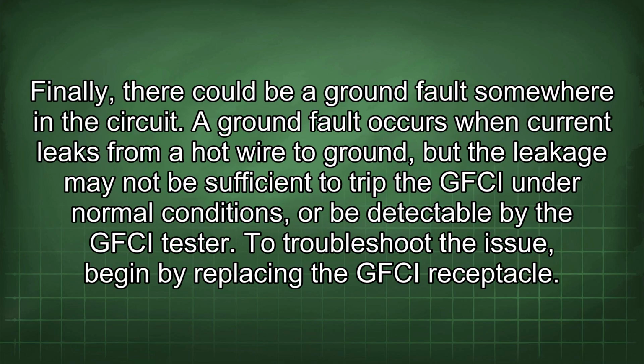Finally, there could be a ground fault somewhere in the circuit. A ground fault occurs when current leaks from a hot wire to ground, but the leakage may not be sufficient to trip the GFCI under normal conditions or be detectable by the GFCI tester.